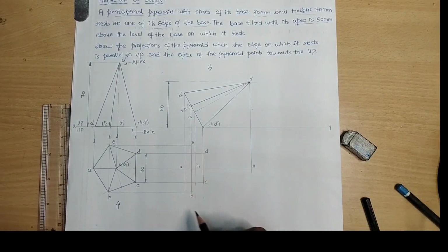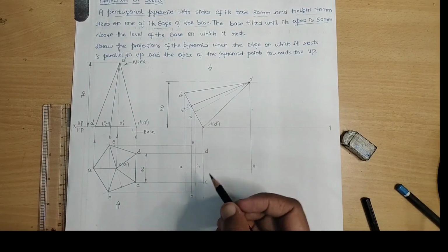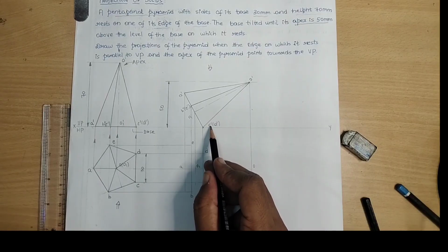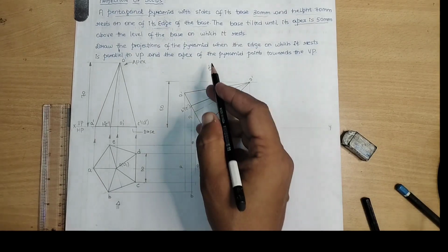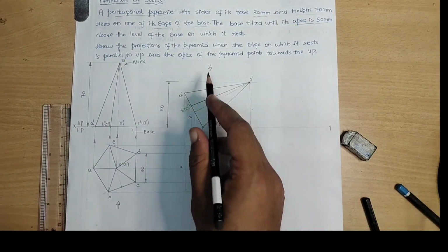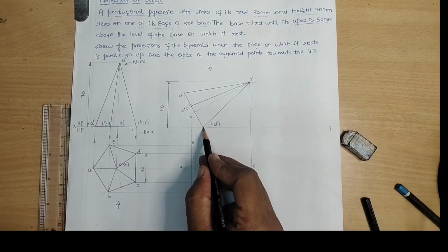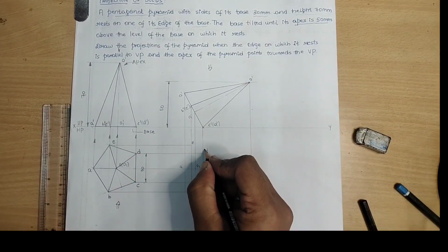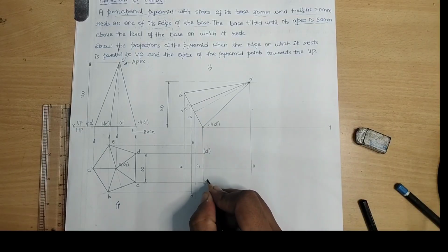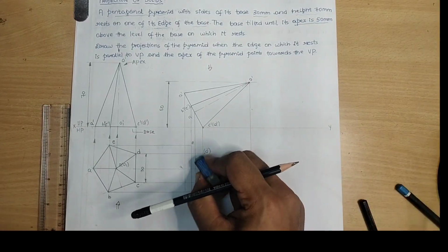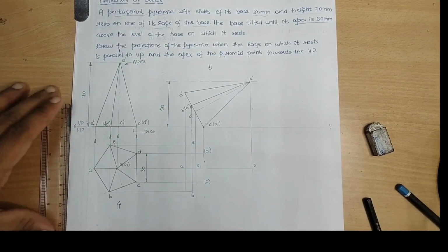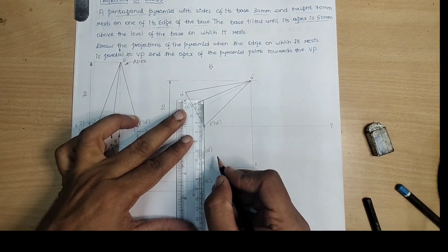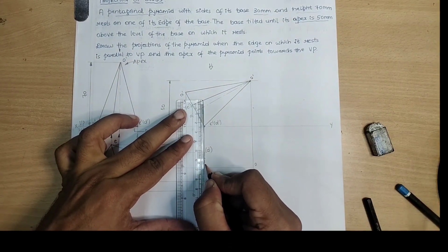What is the condition of the apparent shape? Let us break it down one by one. What is the condition of C dash and D dash? Since the observer is looking from this end, since this point is away from the observer or it is resting on the XY line, C dash, D dash is invisible. Let us keep it in the brackets. And what is the status of C dash, D dash? That will be an invisible line. So the invisible line representation would be something like this.